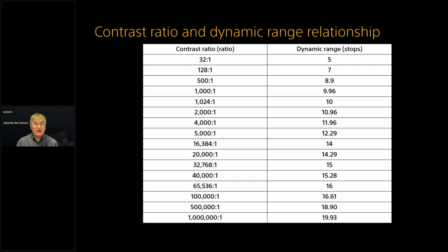So that introduces a question. What is the comparison between contrast ratio and dynamic range? Well, this table here shows us the comparison. It's interesting to note that with 8-bit Rec. 709 high definition television, we're sitting right up here. This is the reason why we're moving towards high dynamic range. We're getting barely 100:1 contrast ratio, barely 6 stops of dynamic range in Rec. 709. Human vision, as I said earlier, is anywhere between 10 and 14 stops, something like that.